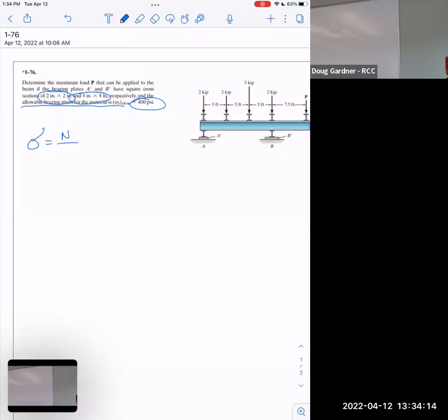This is, and notice I'm not talking about shear forces here. Do you see how I'm not using the tau one? Because these forces are straight down on it. So we're talking about a force that's perpendicular to the surface. So I'm only interested in the normal stress, not the shear stress. You understand that? There's no force trying to get this to slide in that direction. It's all straight down on it, normal to the surface. So that's the only formula I need.